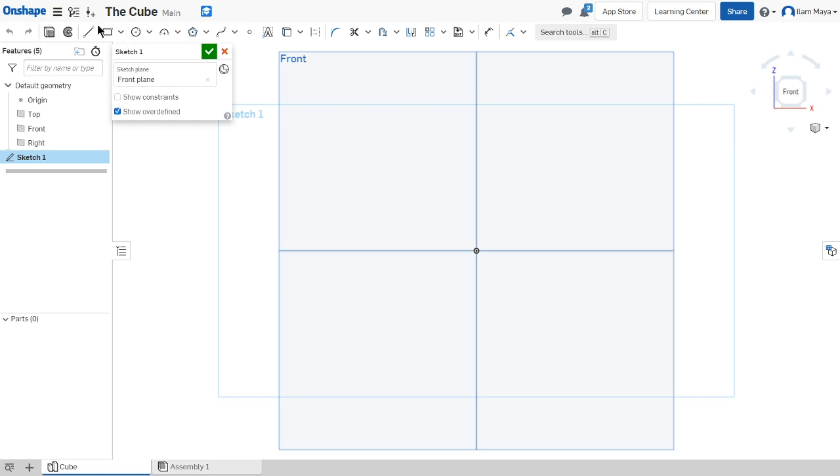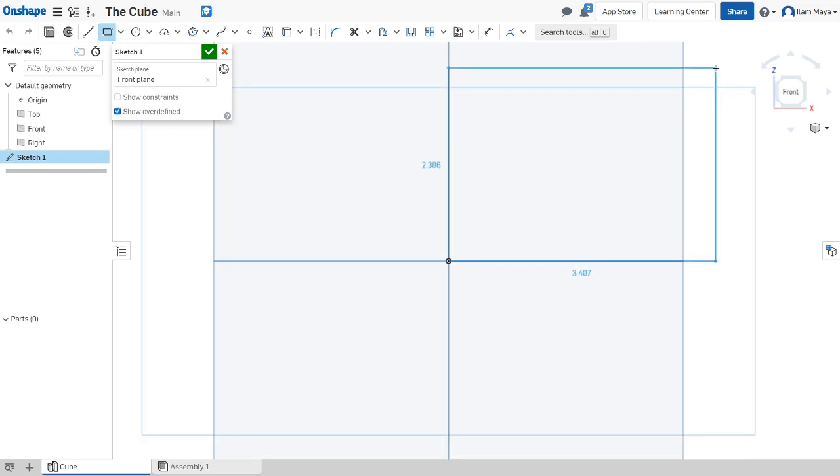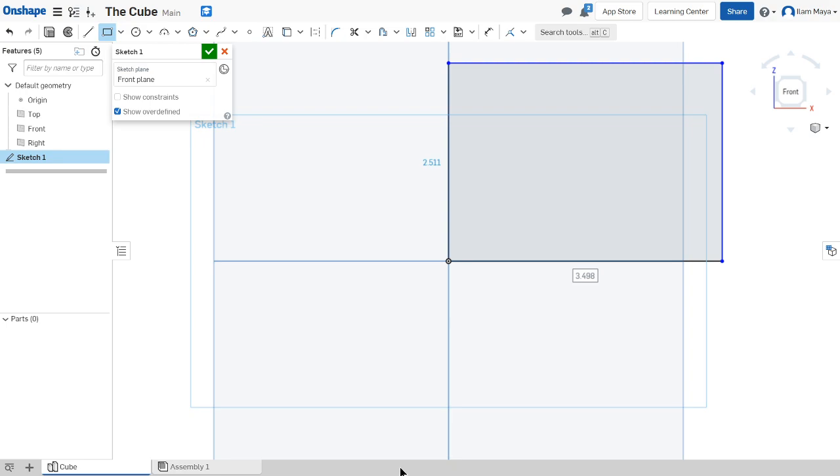But just for the purpose of this video, I'm gonna make this thing called a corner rectangle. But you can also make a square. So I'm gonna click on the origin, and I'm not dragging out. I'm just moving my mouse out, so you don't have to drag it out. And then you click, and you have a rectangle, right?